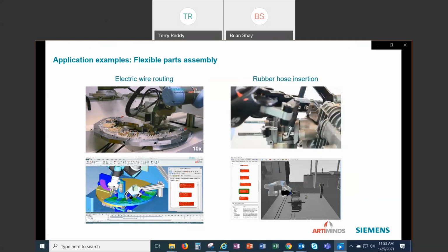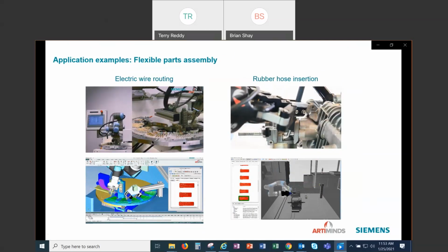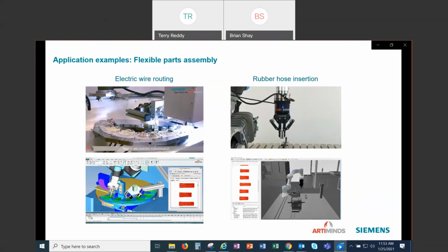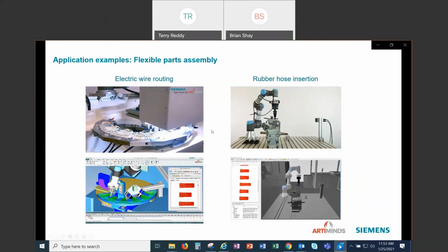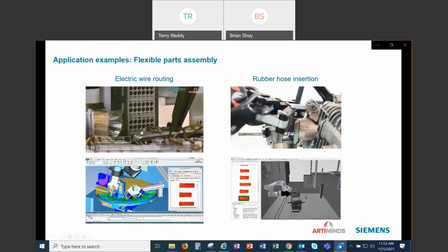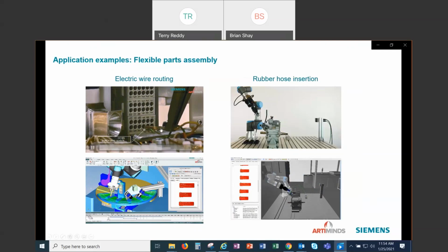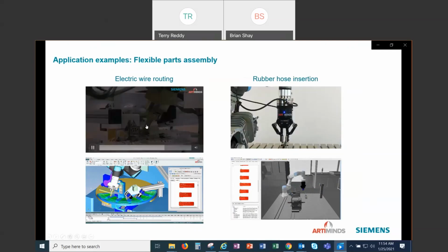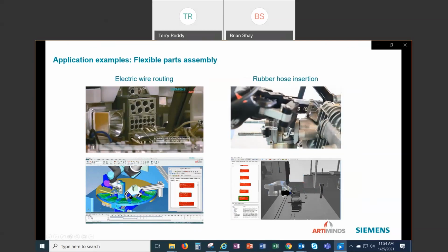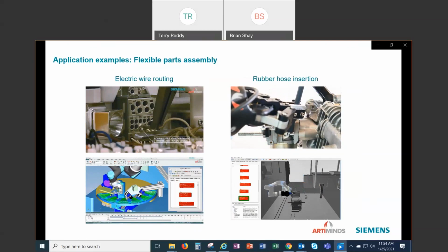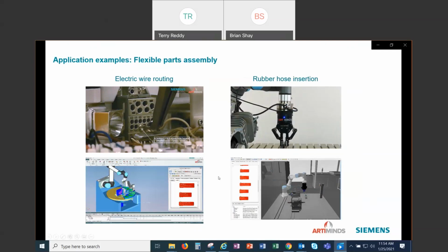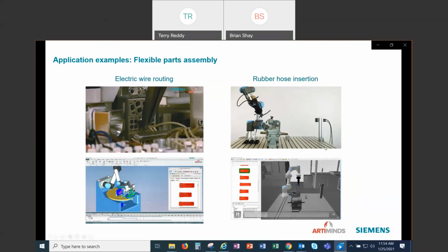It knows exactly out of that to which terminal socket it should go, and then the robot picks this up from the rotating fixture and inserts it into place using, in this case, a spike search approach. And once it's snapped into place, it also performs a pull test to ensure that it's fixed in the connection socket. Again, below you see the simulation of the entire system and the accompanying program.